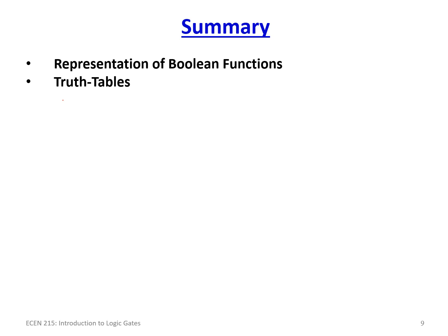So again, if you have 3 inputs, you would end up with 8 possibilities for inputs, which give you 8 rows. So it's 2 to the n power, where n is the number of inputs. If you only have 1 input, then you have only 2 possible outcomes. If you have 2 inputs, you would have 4. If you have 3 inputs, you would have 8, and 4 inputs, 16, so on and so forth.